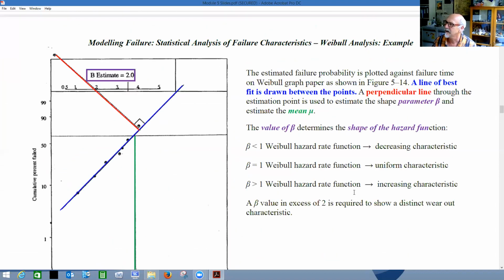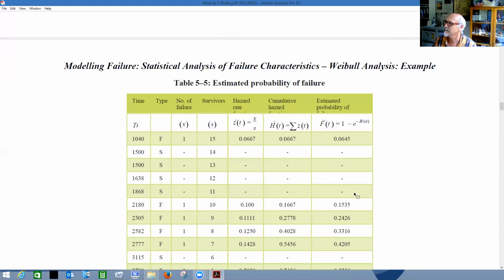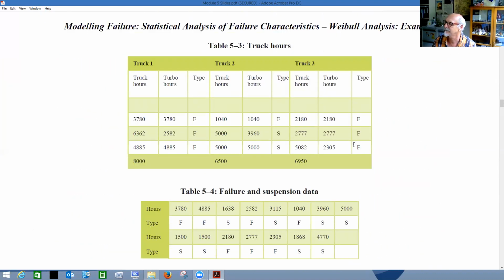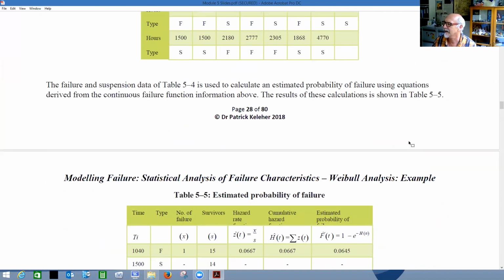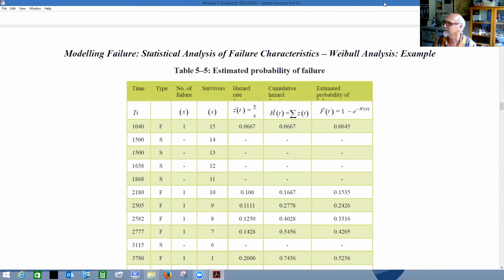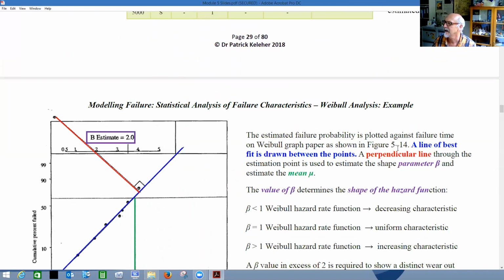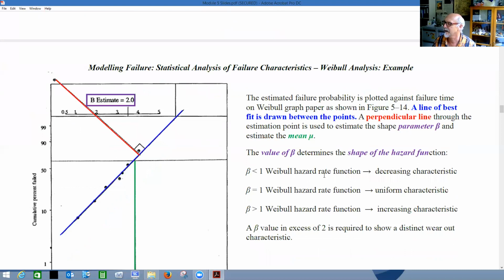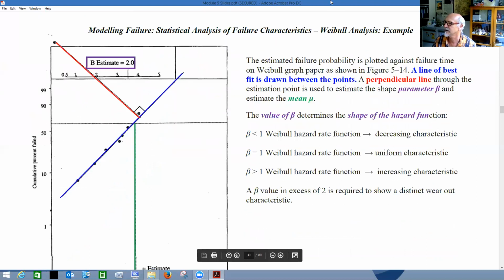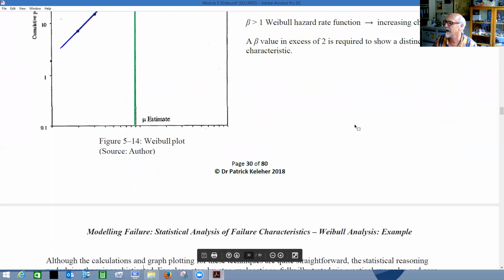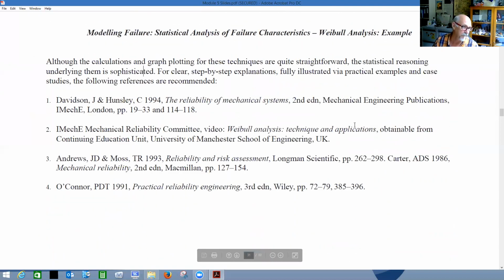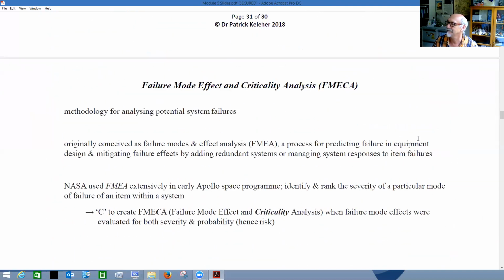So again, just by some very simple calculations and keeping data on site, for argument's sake, you can go about analysing the probability of failure using this Weibull analysis, and of course the graphs. You can calculate averages and overall figure out information that will help you with your scheduling and your planning.